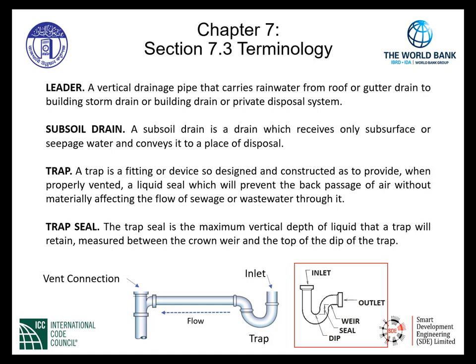The top of the sanitary T is where the vent connection will take place and be piped to an approved venting section of the drainage system.